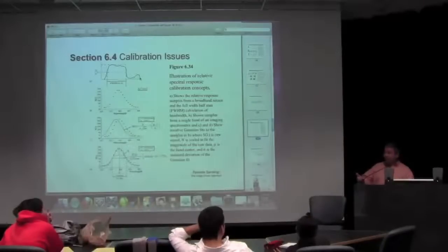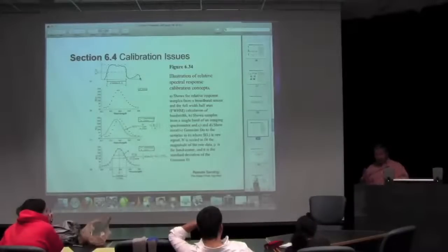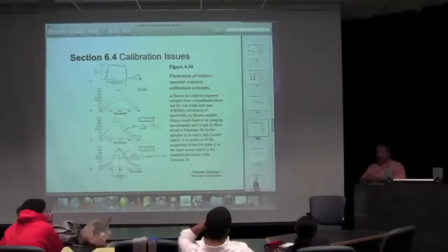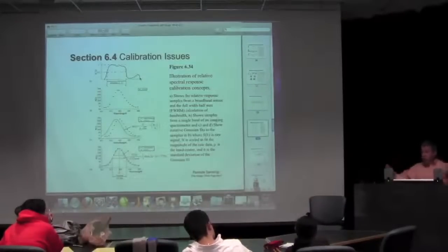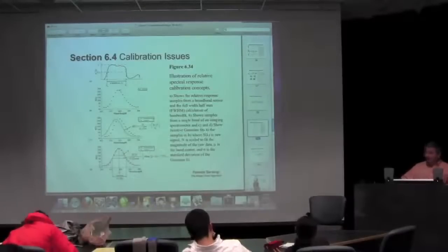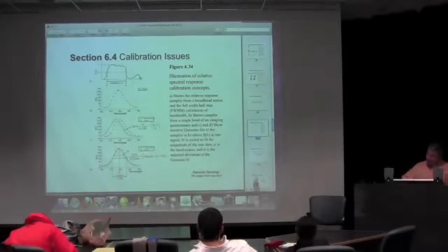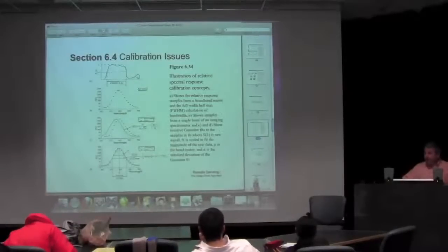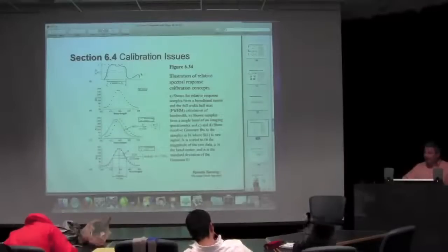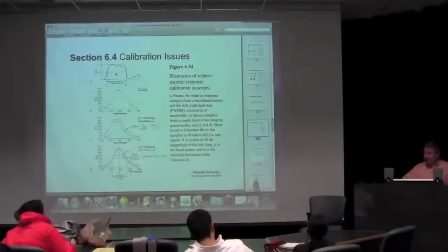So in front of your Bayer pattern that specifies the red, green, and blue pixels that get imaged in your camera, there's another filter called an IR reject filter. That IR reject filter blocks the incoming infrared radiation from the world. You don't see it with your eyes, but there's lots of infrared radiation. It blocks that so that it doesn't oversaturate the red channel of your detector. So you might think of it like this. This might be the response of silicon out in the near infrared. If I didn't block that energy from coming in, then I would actually record that with my red detector and record it in my signal.